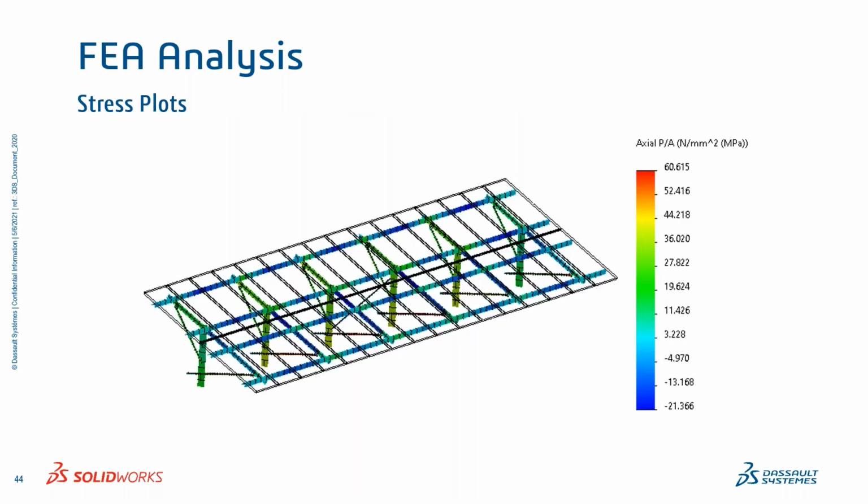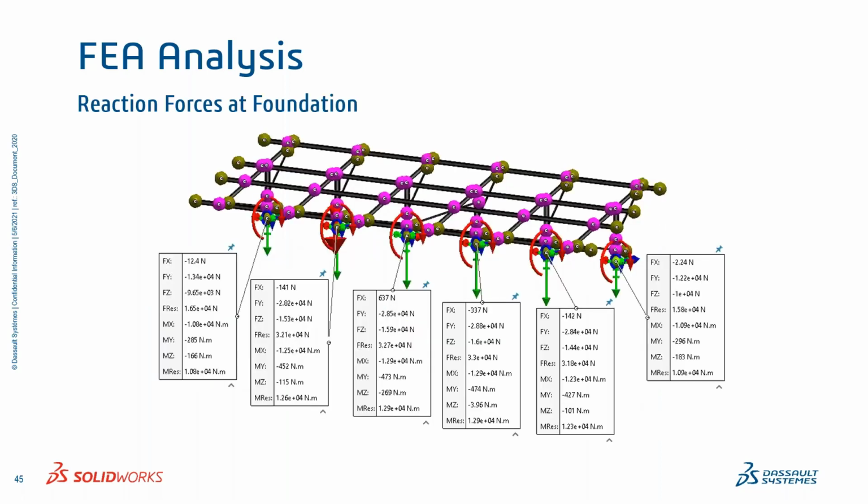And then you can understand the axial stresses, bending stresses, axial force, bending force, moments, torque, and everything can be estimated with the help of finite element analysis post-processing functionalities. And finally, I was talking about the reaction force at the foundation. The reaction forces at the foundation are always very important to decide what type of bolts and what type of connectors we should use at the foundation to overcome the failure of these solar structures.